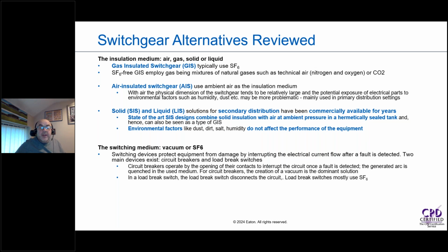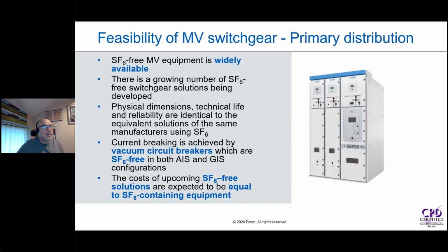So a circuit breaker is designed to open and close on faults. So either open on a fault where there's significant arcing, or close onto a fault. And load break switches are purely designed to break load, nor are they fault make. So there's a couple of subtle differences in the construction internally of the vacuum bottles, perhaps, and also a couple of constructional differences within the SF6 system, be that product deemed as a load break device or a circuit breaker device.